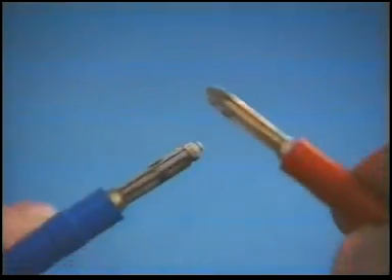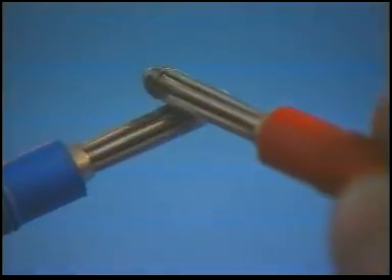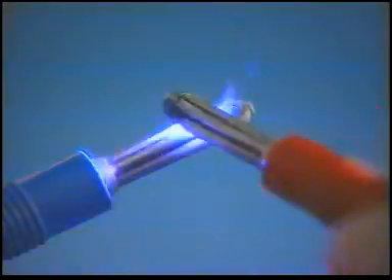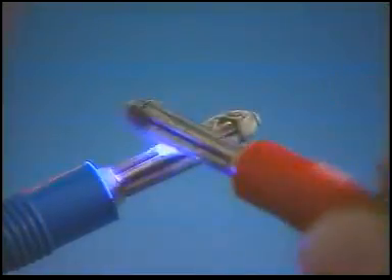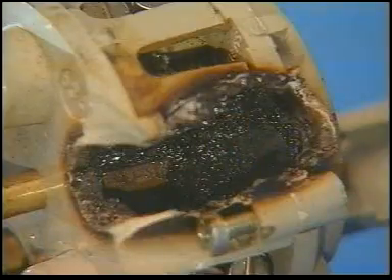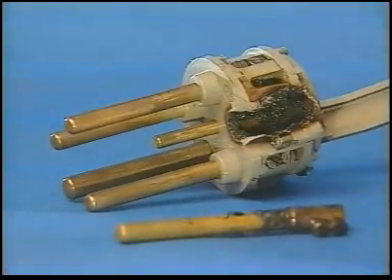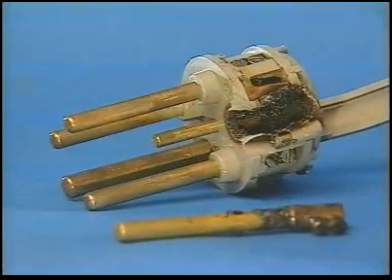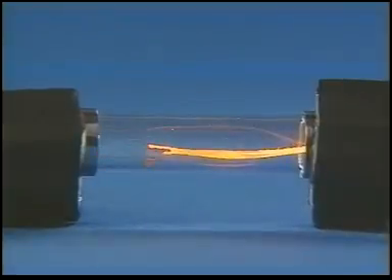And here is a phenomenon that everyone knows, the short circuit. What happens exactly? If in an experiment we connect both poles of a voltage source directly, an extremely large current flows because there is no resistance. The result? Extreme heat which leads to melting of the conductor or other damage. The solution? Fuses are integrated into electrical circuits. The fuse then interrupts the current flow and prevents further damage.